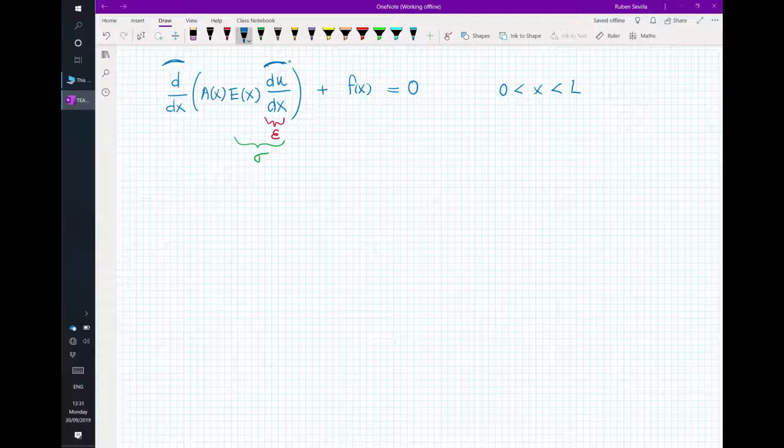So the first type of boundary condition is I know my displacement. The other type is I know the stress. I don't know the displacement, I know the stress, right? And in this case, I'm going to assume that I know the displacement on the left, I know the stress on the right. And I'm just putting another number, 3, just to see how we handle this data. Make sense? Right. I can have Dirichlet at both ends. I can impose the displacement at both ends. Agree? Can I impose traction at both ends?